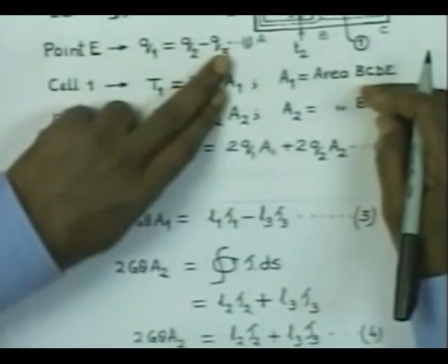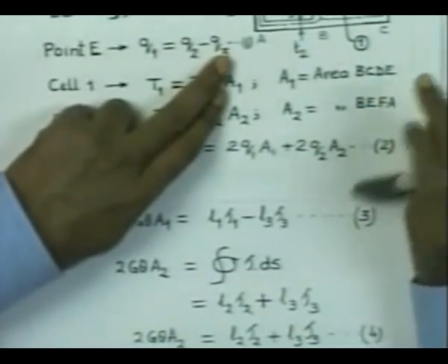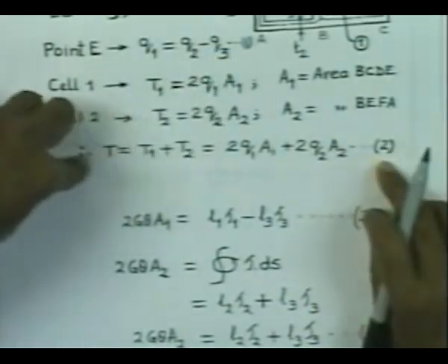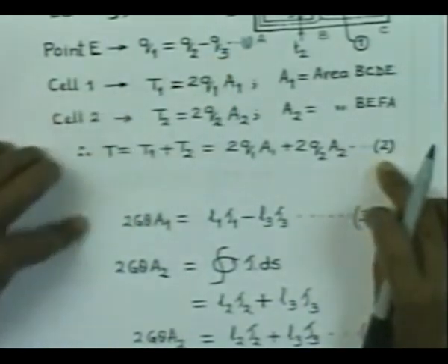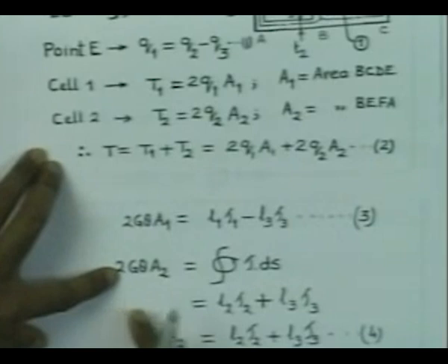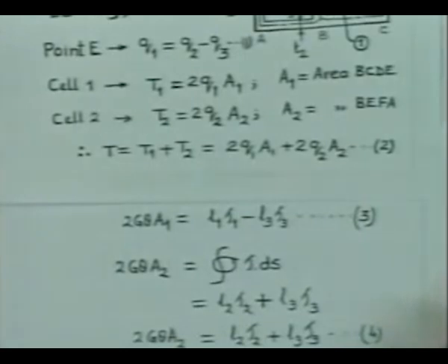We have condition 1, then the torque related to the flows, and the angle of twist related to the shear stresses. Therefore, you have the unknowns, the 3 shear stresses or shear flows and the angle of twist, and you have 4 equations, so you can solve for them.